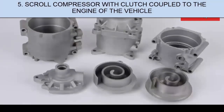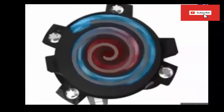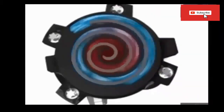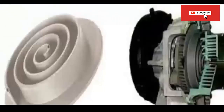5. Automotive scroll compressor with clutch coupled to the vehicle engine. In the figure we can see how the volume of gas in the scroll compressor is progressively reduced. It has an orbital displacement. Compression is done by volume reduction. The compressor assembly is made up of 2 spiral-shaped rotors. One of them is fixed in the casing and the other is mobile, driven by the motor. They are mounted 180 degrees out of phase.